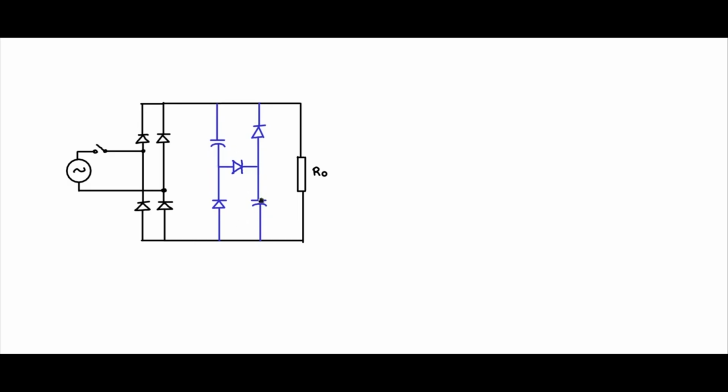The charge is divided equally between the two capacitors if the two capacitors are equal, and the two capacitors will independently discharge into the load. So the diode steering network takes care of this issue. So let us call this C1, this is C2, X, Y, and you have Vi and V0. So let us look at the wave shapes at various nodes to understand this a bit better.